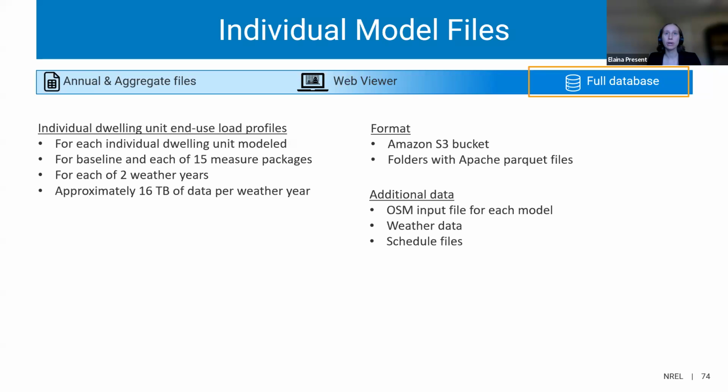Are the ducted dwelling units in Measure Package 4, which is the existing backup, the only use case with a compressor lockout temperature? Every heat pump has a compressor lockout temperature. Its default, I believe, is -40 degrees Fahrenheit. So it's not going to get triggered that much. So to answer your question, technically, no. It is the only heat pump with a compressor lockout temperature that is seen frequently in our weather files.